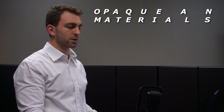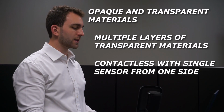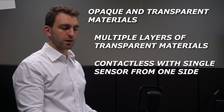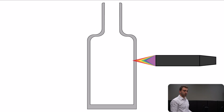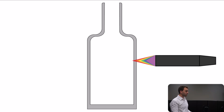And this brings me already to the biggest advantages of such a confocal system, because not only can we measure various transparent materials like glass, polymer films or similar, we can measure multiple layers of them, and we can do all of this contactless with a single sensor from a single side. So compared to other measurements, you can now measure all these details even with high space constraints. For example, when we look at a glass bottle and want to measure the thickness of it, then you don't need a second device which goes into the glass bottle, because you can measure everything from outside of the glass bottle. I guess this makes it clear why the confocal sensor is also a winner in the glass industry.